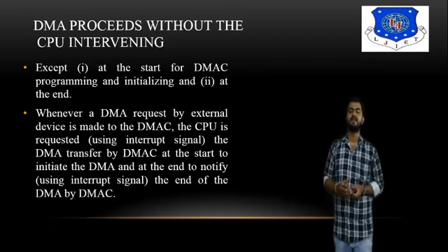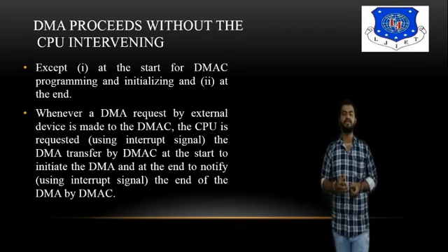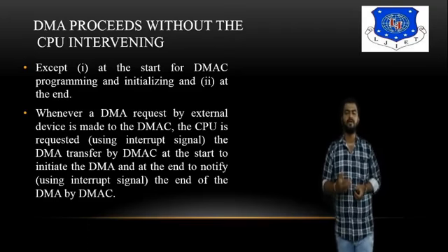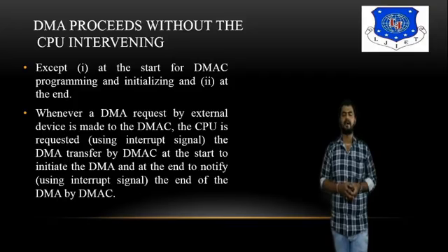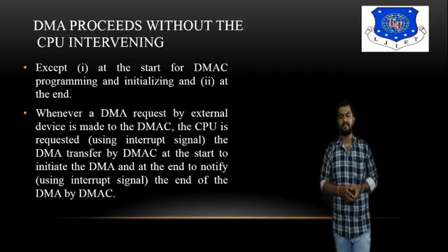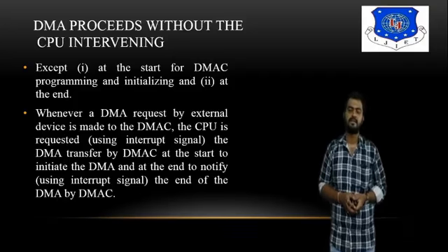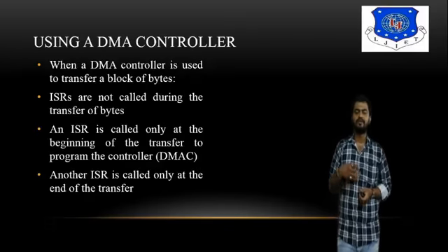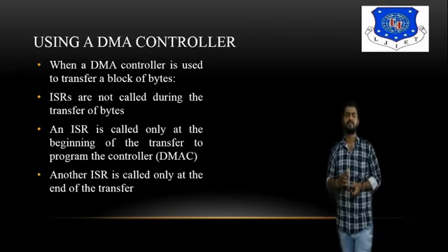The DMA transfer by the DMAC: at the start, the ISR initiates the DMAC, and at the end, it notifies the end of the DMA by the DMAC, meaning the direct memory access controller. Now, if we are talking about the DMA controller, then we have to follow a few steps.